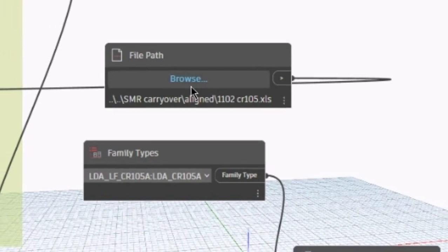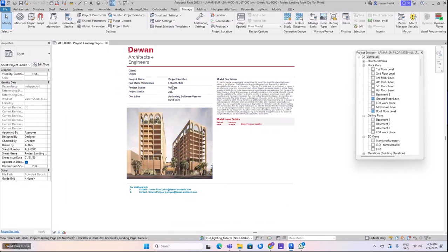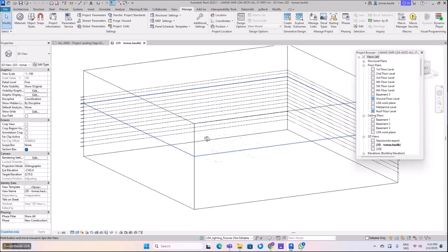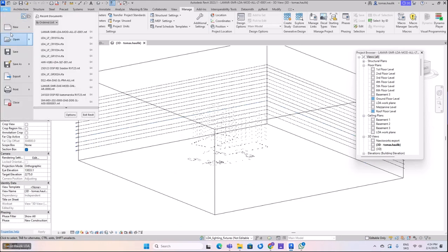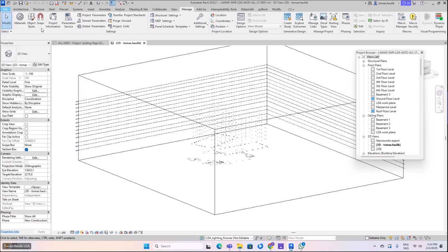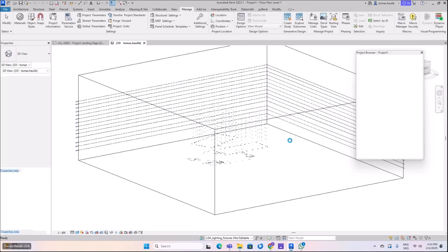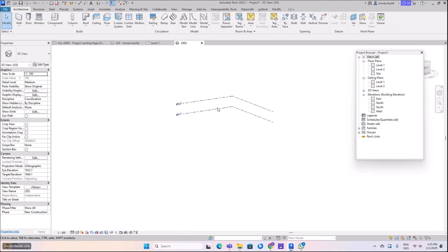extracted from DWG. First, what we need is our file setup, which for SMR we have, and then to navigate into the 3D view. Then, since the plugin is not perfect yet, we actually need to open another project, just not to make a mess in our project. Good to use the metric architectural template. And also navigate into the 3D view.